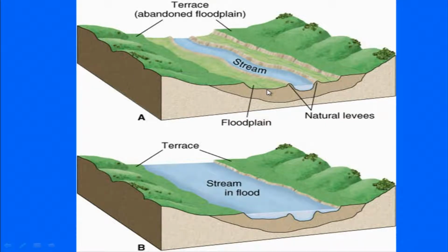Now one important thing which we should remember, that these are all the older abandoned floodplains. So this location, people usually, or in most of the areas, people have been using such regions or the areas for construction or housing purposes as well as agriculture purposes. But these are the areas which are the abandoned floodplains and can be occupied by the stream in flooding state. So if you have peak floods, so this whole area can be submerged.